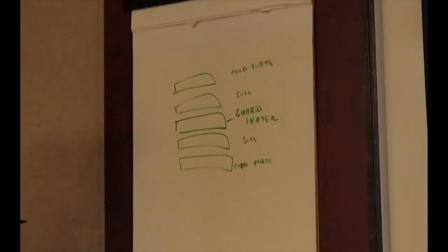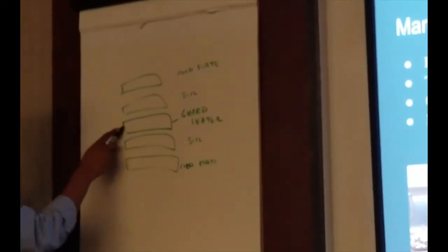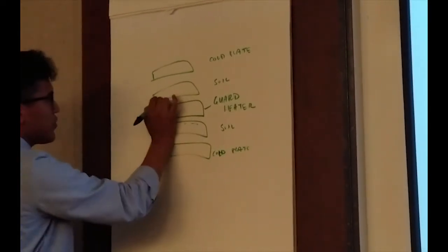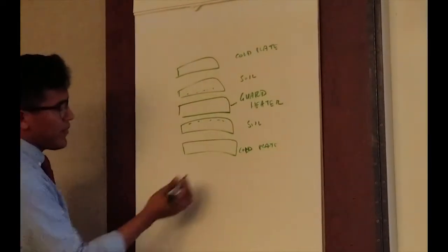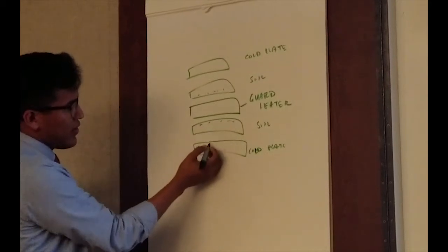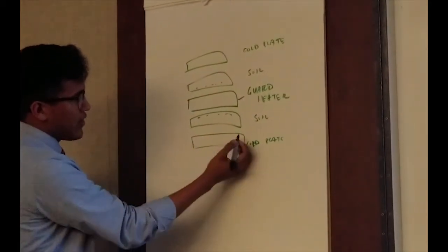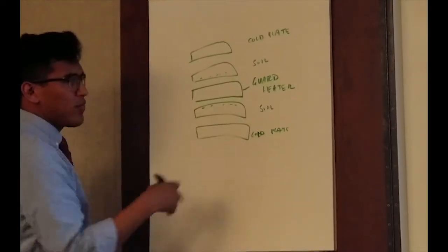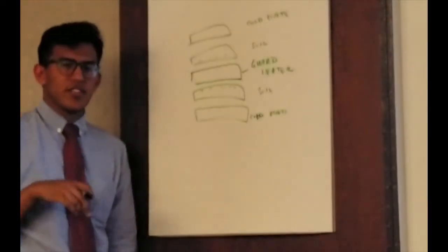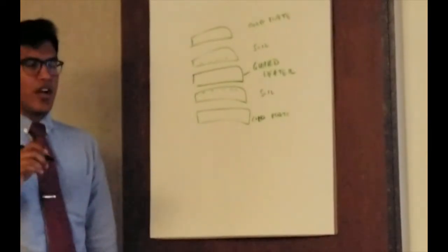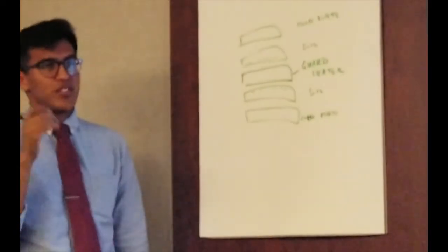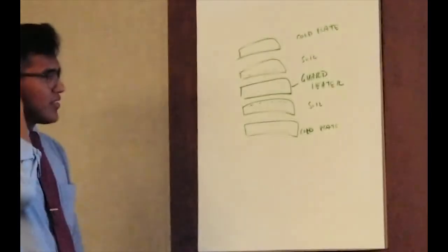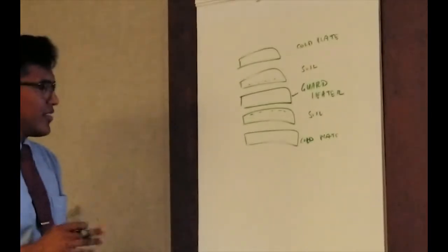Now, the guard heater generates the heat, and we put little sensors on the soil specimens that track that, and then this is the cool side, I suppose, so that way, going back to the definitions, you realize how much energy it requires to raise it 1 degree in temperature. So that was the whole premise of this test.